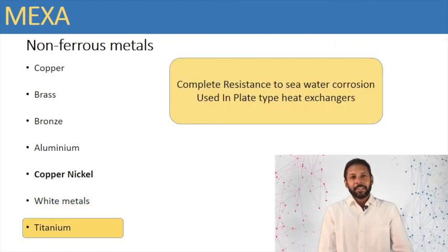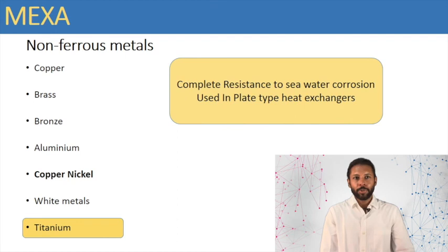Titanium. Ideal where resistance to erosion and impingement corrosion are the most important requirements. It is virtually completely resistant to corrosion in seawater. Only under exceptional conditions of erosion would the protective oxide film be damaged. When alloyed with about 2% of copper, a moderate increase in strength results. It is widely used in heat exchangers, especially the plate type.